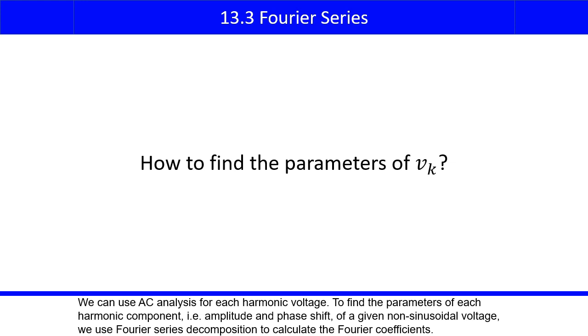We can use AC analysis for each harmonic voltage. To find the parameters of each harmonic component, those are amplitude and phase shift, of a given non-sinusoidal voltage, we use Fourier series decomposition to calculate the Fourier coefficients.